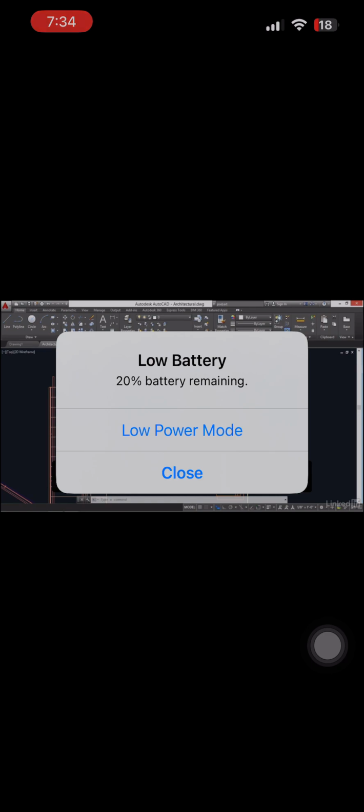This time, I'd like to rotate the chair here using a set number of degrees. Click Rotate, select the chair, press Enter, specify the base point more or less here in the middle of the chair, and we'll type in 30 for 30 degrees and press Enter. So it's just that simple.